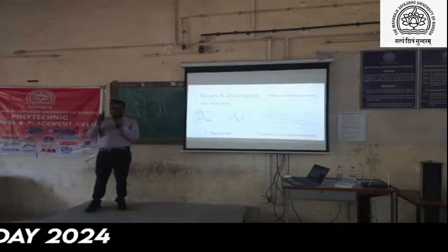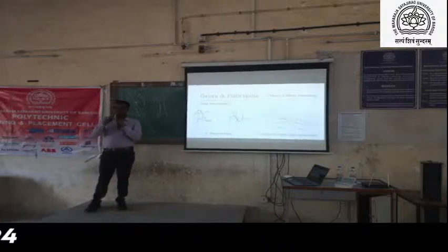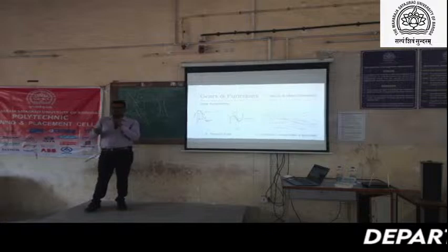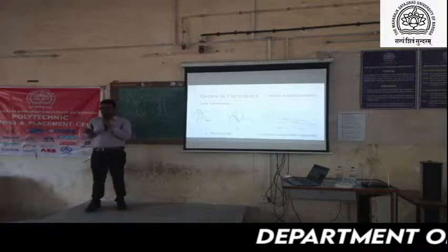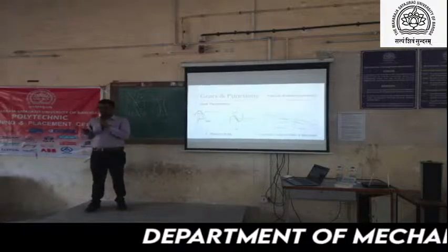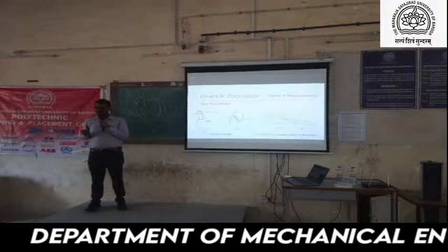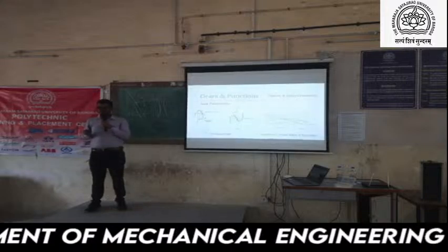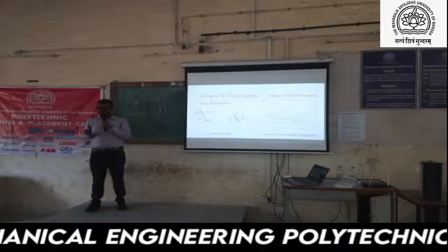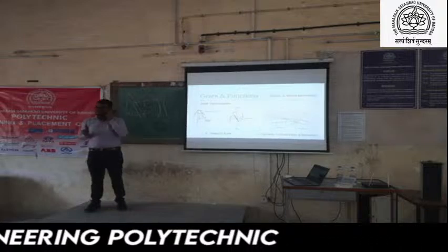Exactly right. Do you know why we are using spur, helical, bevel, and so on? Why are we changing that? Because we have different load carrying capacity.